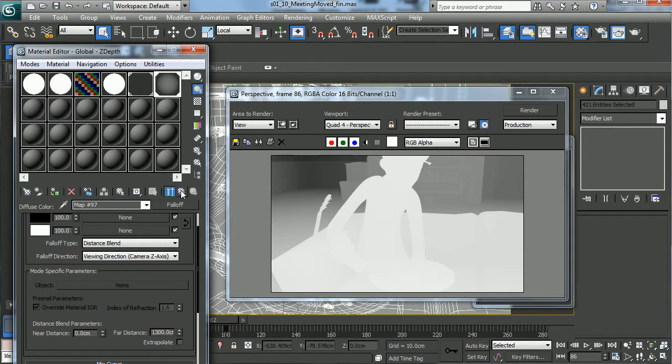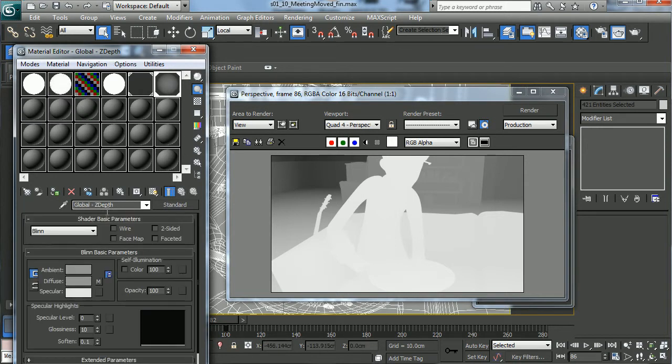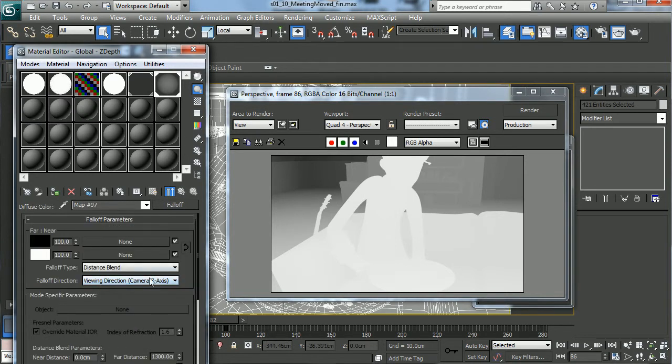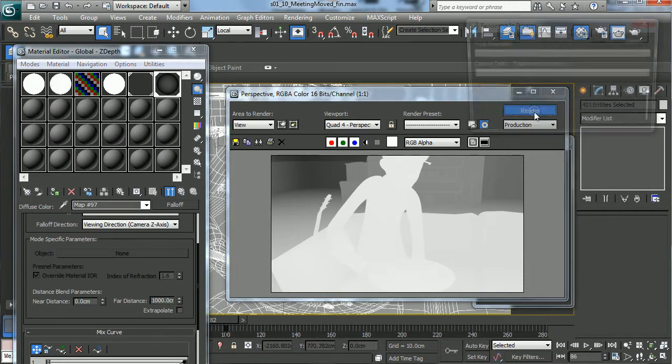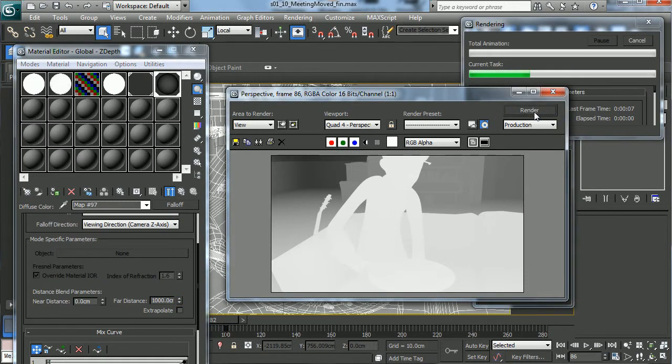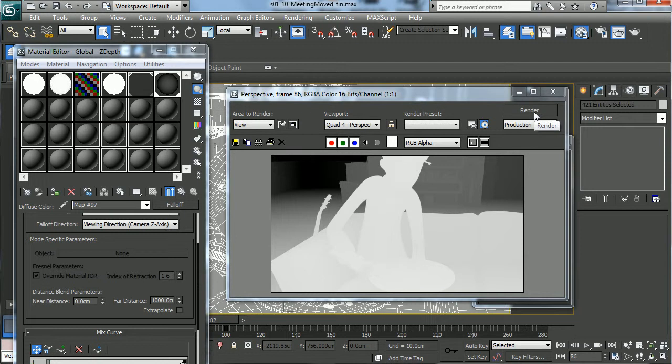And so if we select our global depth, click on the little M, this will take us to our falloff map, and change the far distance to one of the values that were provided in the document. We want to be consistent with this because it'll make our lives a lot easier in post. So here we have a little bit of a better range, especially in the foreground here. Now we will be saving these as 16-bit TIFFs, so we should have some flexibility.